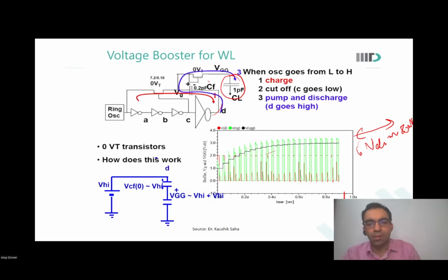Sir, in the early read operation in the last lecture, we saw that CAS will come later, but there was junk because the output was high. So how will that be distinguished from junk, data out and junk? Like the output was high, no? So junk you don't bother about. You simply latch the output only after T access.